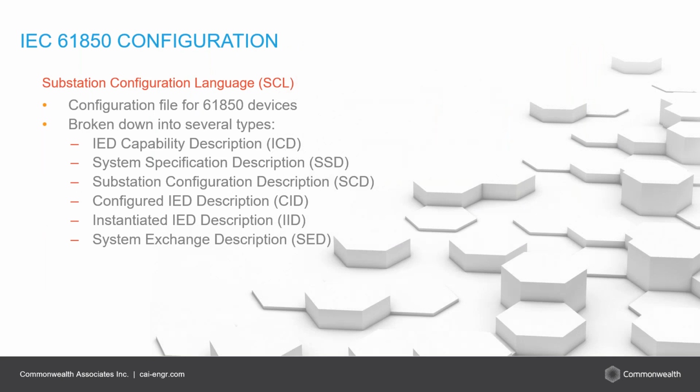Okay, so the IEDs which connect to the network would need to be configured so that they work on the 61850 network. Now, configuration tasks would include setting up the relays or IEDs to transmit and map the GOOSE messages, subscribe to particular data sets, and map data objects to protocols like MMS.